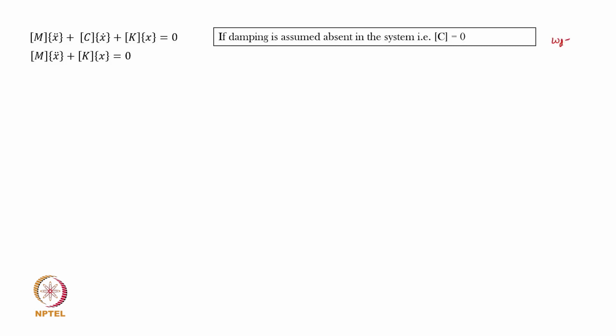It is omega n square root of 1 minus zeta square. Now, zeta typically for mechanical systems, unless you intentionally put a very heavy viscous damper, most of the times if it is structural damping or even damping using a dashpot, zeta is going to be a fraction, and the square of that fraction and then square root of that whole number is all going to be indicative of the fact that omega d is quite close to omega n.